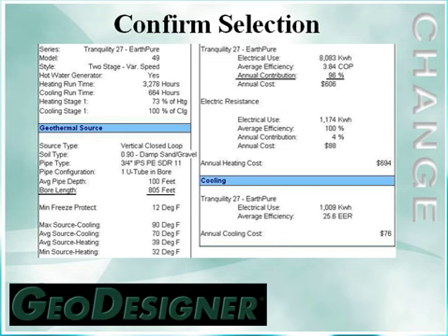Our cooling operating cost is also shown in this screen. In this example, I used the Indianapolis weather market area, which is my home territory. I'm probably going to run on low stage cooling through most all of that cooling season. If this is below 90% of the annual contribution with geothermal, I'd select the next bigger unit and look at our operating cost and whether we're getting to that mid-90 range.